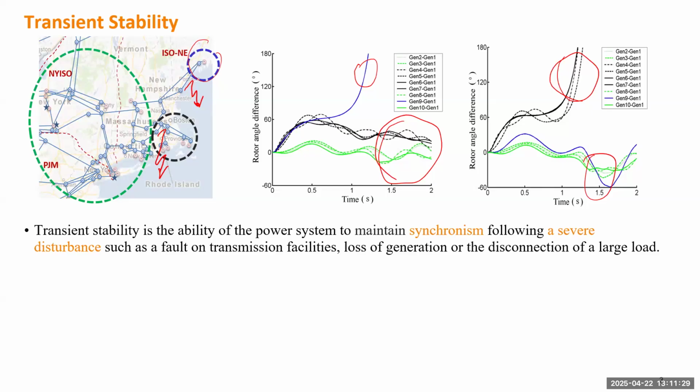You can depend on the balance of load. You want to decide whether to reject some generation or trip some load to maintain the rest of the system operating at 60 Hertz. But for the second scenario, you may not be able to trip everything in that group. If you cannot save the system by load shedding, you may have to do islanding, right? You have to form an island for that out of step group of generators to operate on their own. But that is a more critical condition.